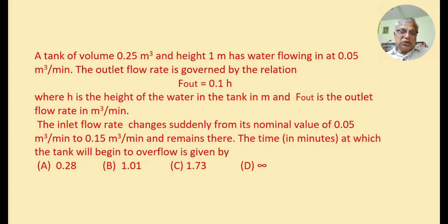Well, this is related to the dynamics of a tank because the inlet flow rate changes and you're asked to find out the dynamics, the response of the height of the tank. So we need a transfer function relating the height and the inlet flow rate of the tank. The tank can have different types of transfer function depending upon the characteristics of the flow between the flow and head, that is the flow head relationship.